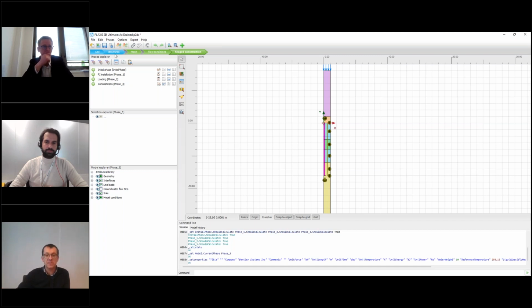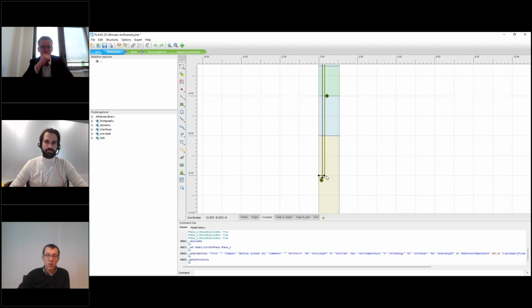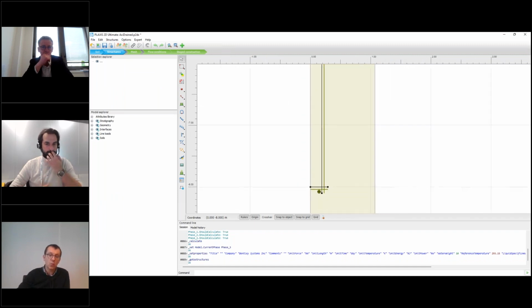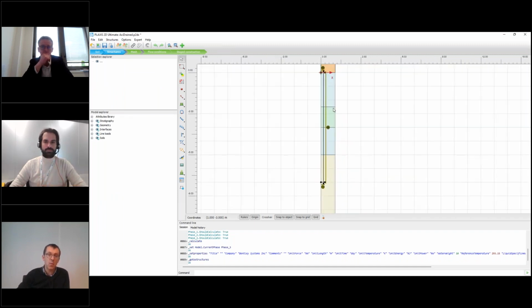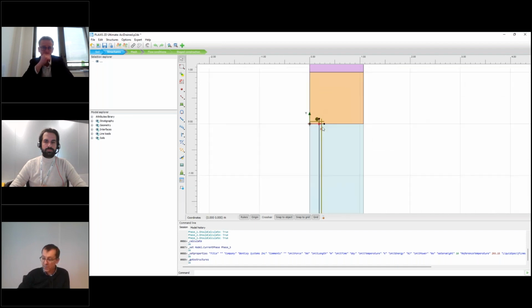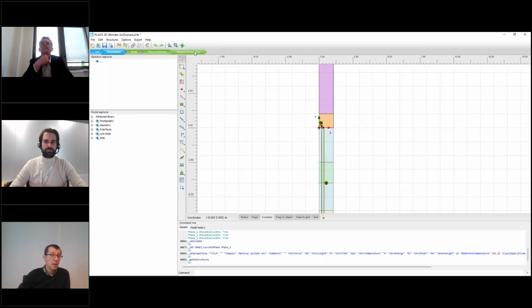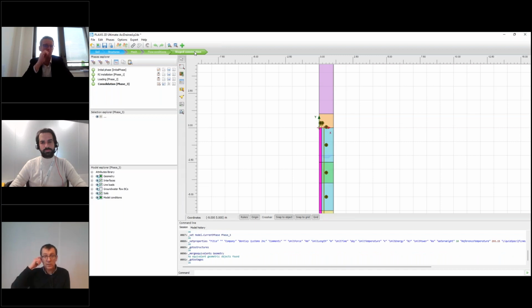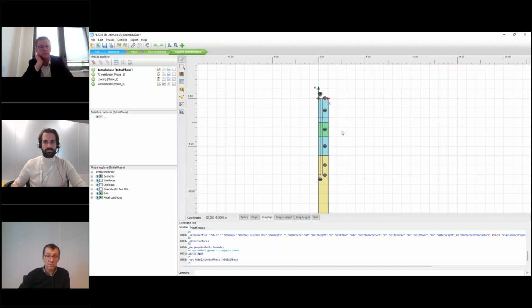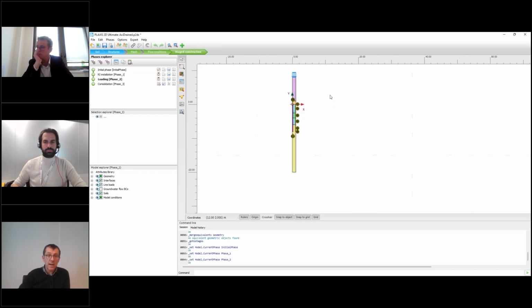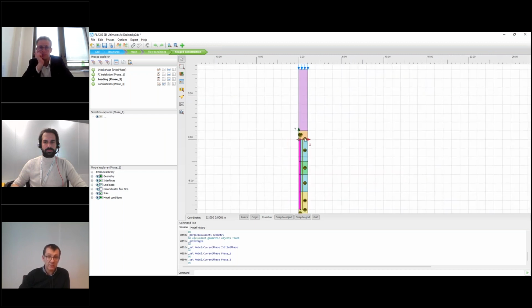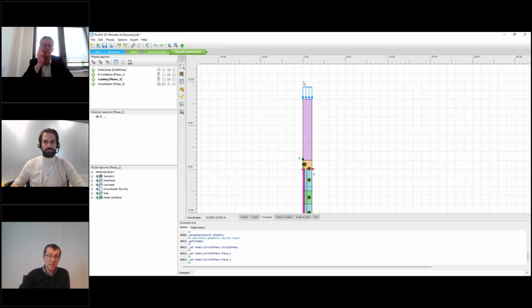Here there are some specific characteristics of that model. Note the use of the small extension, although this is not very relevant, but it is something I always introduce. If one goes to the stage construction, I first have an initial phase, where I just place the soil in place. Then I activate the rigid inclusion, and then apply the load. So that's the mattress, that's the embankment, that's the service load, and finally a consolidation.